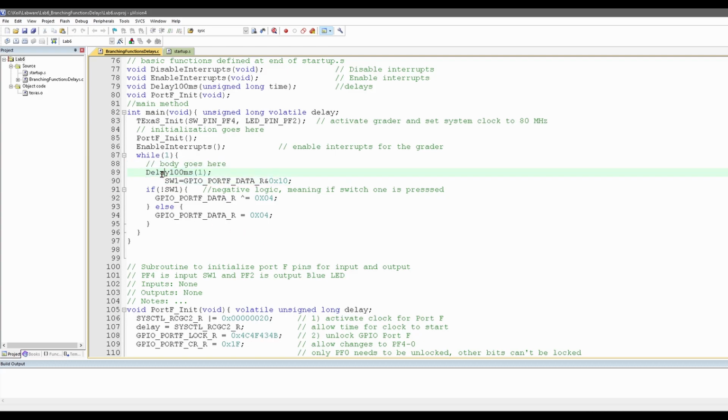First thing that we're going to want to do is delay this by 100 milliseconds once we press it. We know that when we press it, we want to delay 100 milliseconds. So this might be able to go inside of here. We'll test that in a second. But we have this dirty delay of 100 milliseconds where we pass in 1. We'll come back to just the 1 in a second.